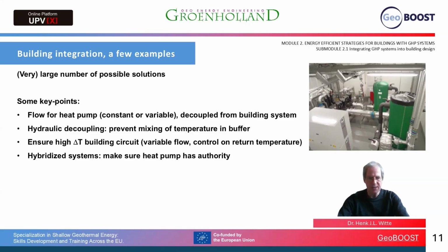And with hybridized systems, this becomes even more important. Make sure the heat pump has authority and not that when the gas boiler comes online, the return temperature increases, or when the chiller comes online, the return temperature decreases very quickly.